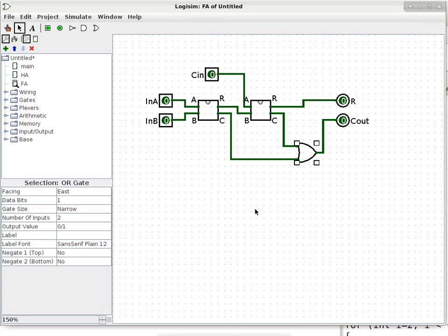Now we have a full adder. Out of a full adder, this is one single column. Okay, you can handle the addition of one single column. What do I do when I want to have a 4-bit adder? We stack up 4 of these things, right? Yeah. So we can now use this as a component.